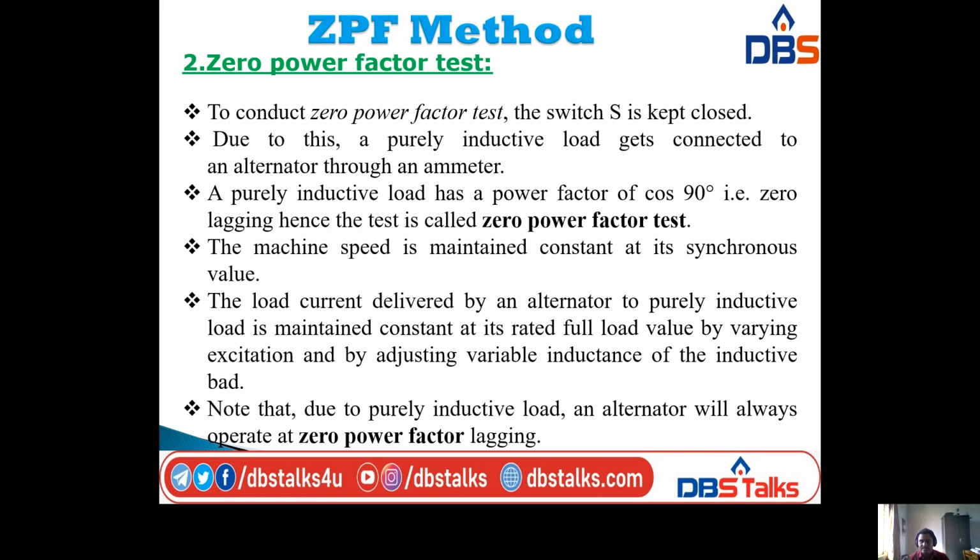That means a purely inductive load has a power factor of cos 90 degrees, that is zero lagging. Hence, this test is called the zero power factor test. Next, the machine speed is maintained constant at its synchronous value.